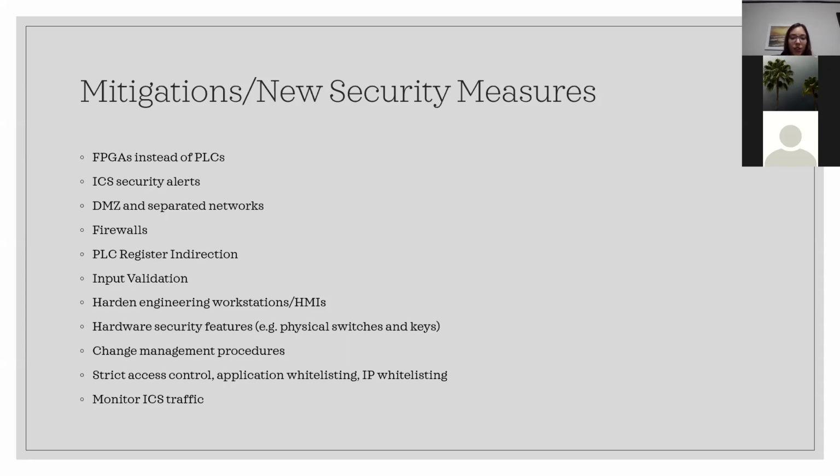Then hardware security features. So some PLCs actually have physical switches that change their mode. So they can't actually be programmed or updated while their switch is in a certain position. So you have to physically turn the switch to some sort of edit mode in order to update the firmware or modify any of the PLC's registers or anything like that.